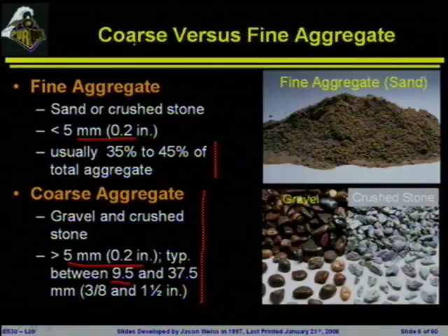Any other reasons why they wanted to make it smaller? For example, in the state of Indiana, driving on Road 26 out to the mall, every 18 feet, your car undergoes that joint, a lot of joint damage. One way that you can make the aggregates more resistant themselves to freezing and thawing is to classify the aggregates, but also to use smaller aggregates. Bigger aggregates are more susceptible to things like cracking. They're a little bit harder to mix into the system, so there was a big drive to use smaller and smaller aggregates.